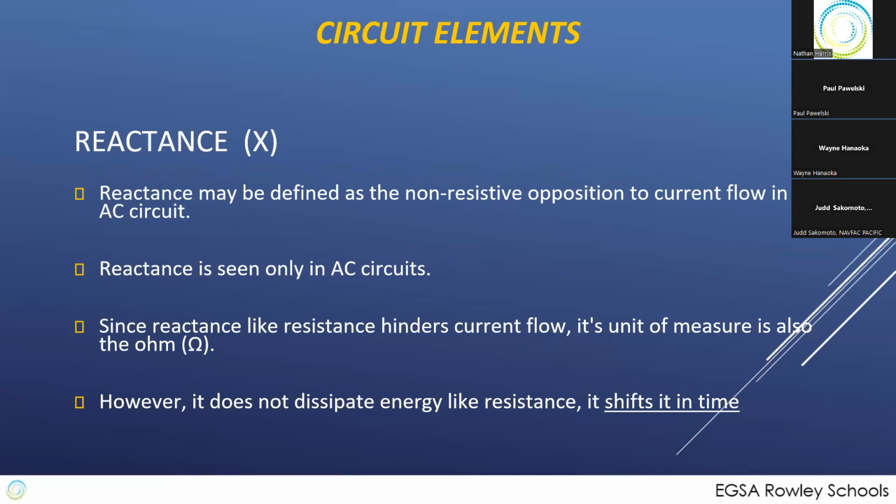So one of the things that you're looking at is these things are not dissipating power like resistance. It's the shift that's making it so that power that should be available isn't there, because the voltage or the current is being shifted in time. Now, this is important because it means your engine doesn't have to be bigger to make up for this phase shift.